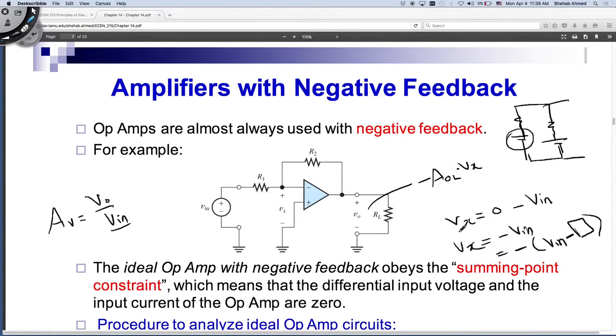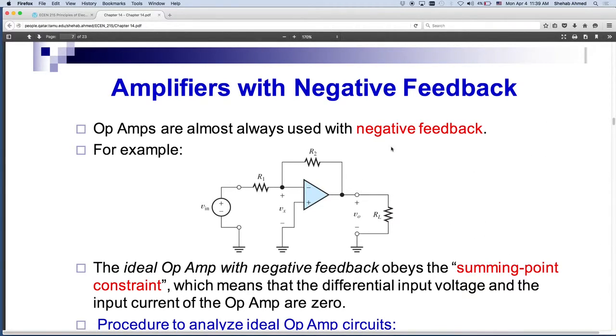If I take a complete short circuit, I'm bringing all the voltage at the output to the input. If I put a resistance, I'm bringing part of the voltage of the output to the input. So I can negate it completely by bringing all of the voltage, or I can bring most of it back and negate it for the most part. If I make Vx equal to 0, then my output no longer depends on the open loop gain.